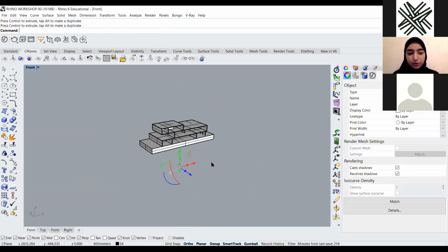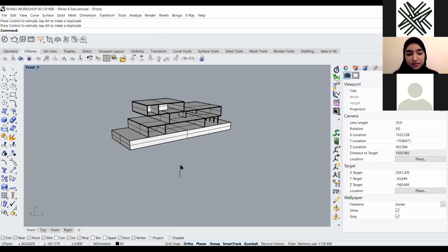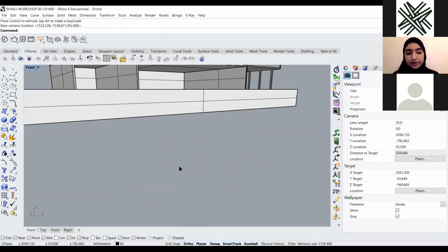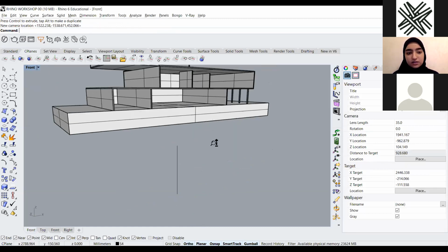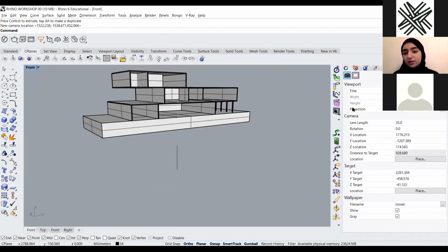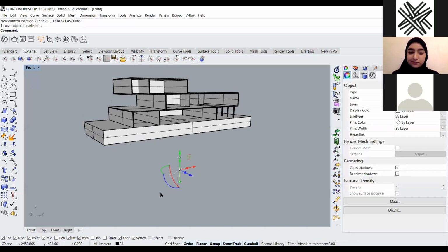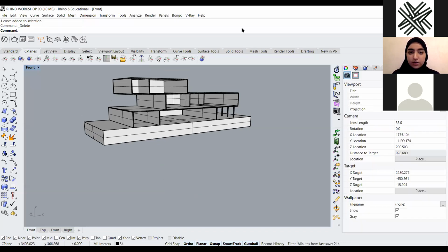What you can do is set the camera target here and let the whole view come from this side. There's something called camera target. So use this option, place, and then click on the top of your line. And as you can see, it doesn't always give you a good result. So I don't recommend it. I recommend using all of these other options.